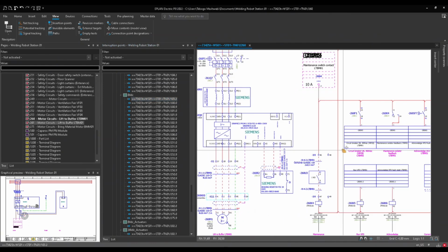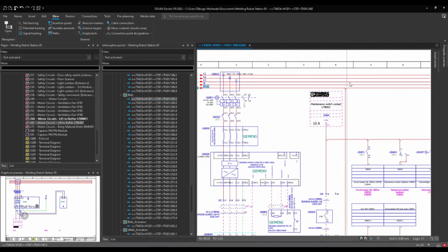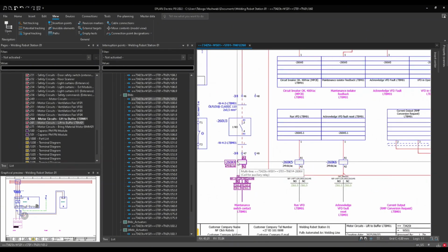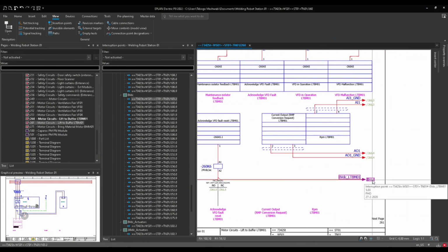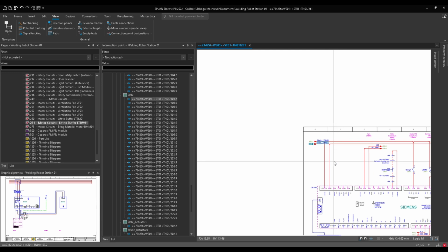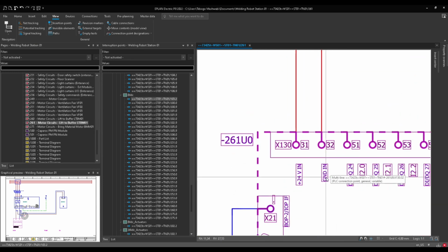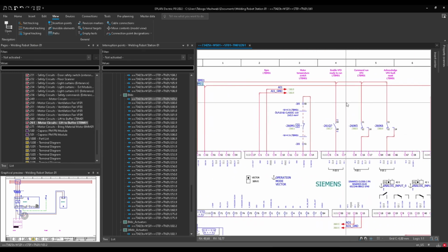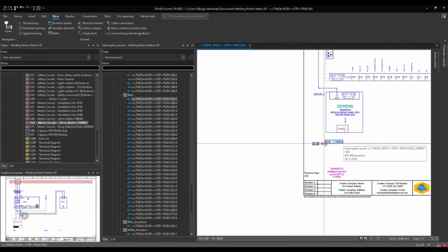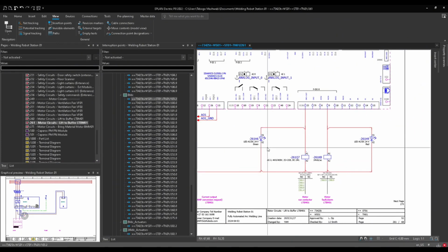We feed different devices, and you can see this one flows like this and flows to the bottom, feeds those relays right there. Those relays get 0 volts, and then it goes to page 261. From page 261, it flows like that into our drive, giving the 0 volts where it is required. After that, it flows like that to here, and from here to here. And then from here, it flows to our LEDs and also our contactor and the relay. And therefore, that's where it ends.